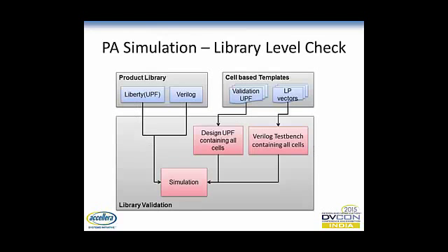To verify those things, we have proposed a library level check where you feed in the Liberty and the Verilog views, and we provide the validation UPF and low power vectors for each cell. Using these, there's an inbuilt infrastructure at ARM, which we are using to translate that into the design UPF containing all cells and the testbench containing all cells, which we feed into the simulator.